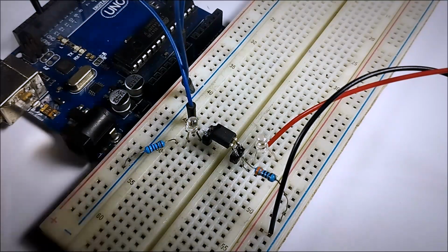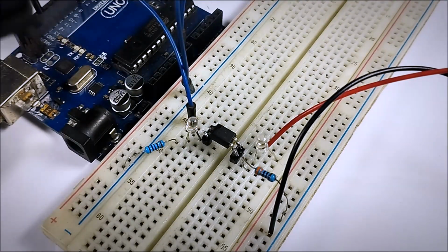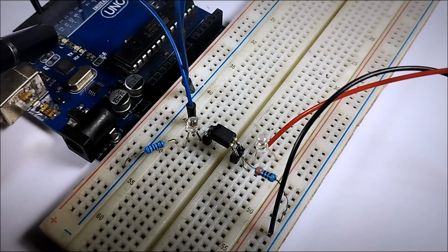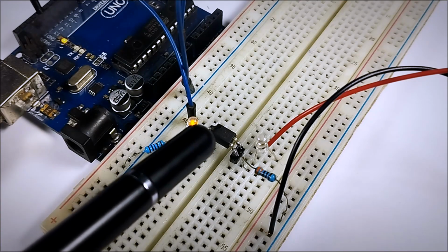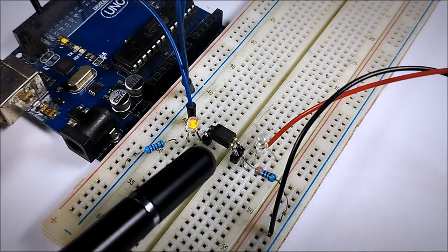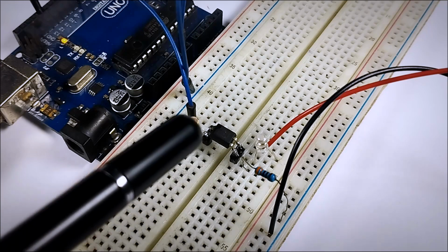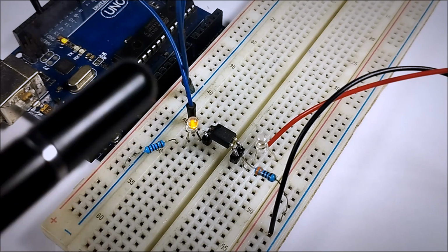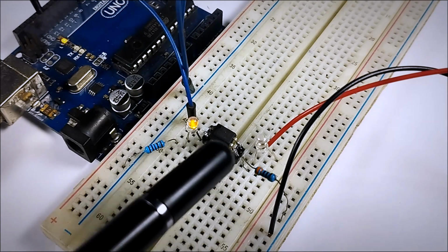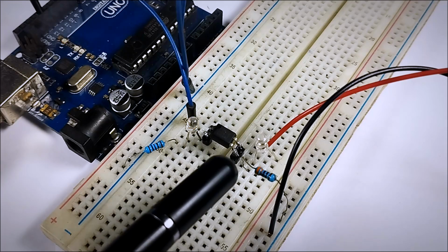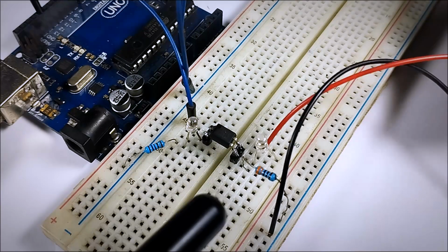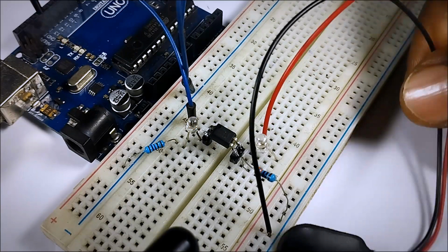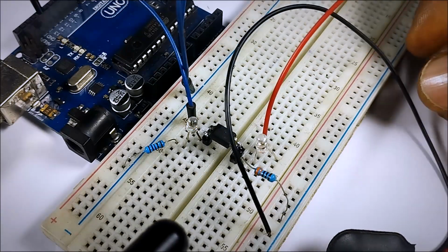And we see our LED blinks, and it blinks just together with the LED on the Arduino. So this is what's happening within the optocoupler, or the opto isolator, right now. The LED within it is blinking and sending signals to this part of the circuit to allow current flow through it. But we don't have a complete circuit here because we have nothing connected to our circuit. We have no power source.